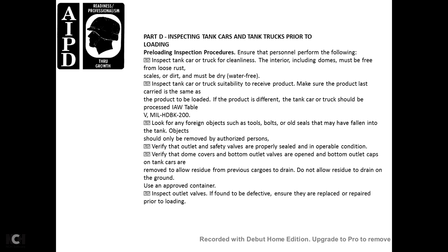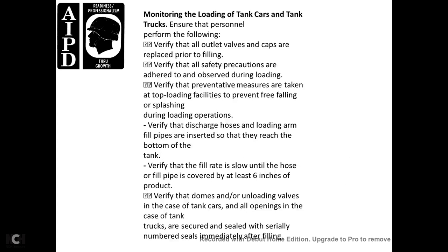For tank cars, remove all residuals from the previous cargo. Do not allow the residuals to drain onto the ground. Use an approved container and inspect outlet valves. If any are found defective, ensure they are replaced or repaired prior to loading.